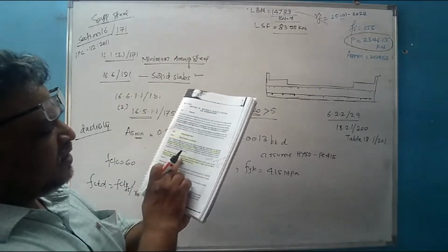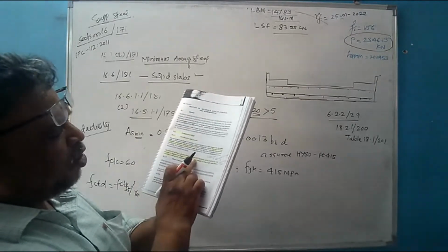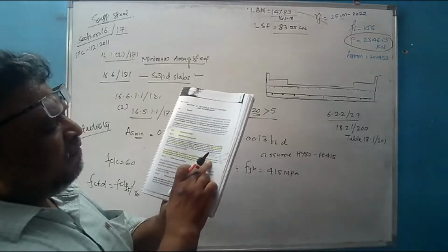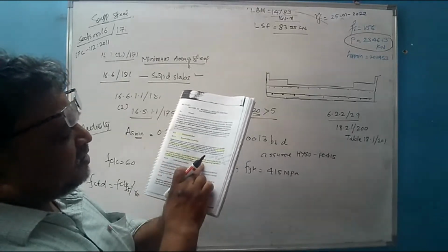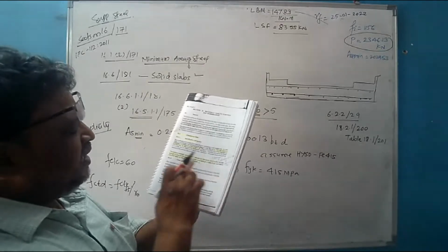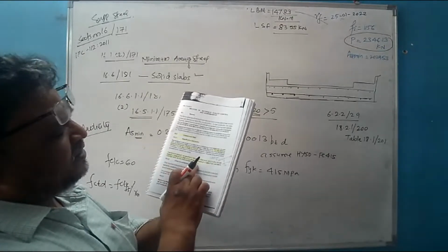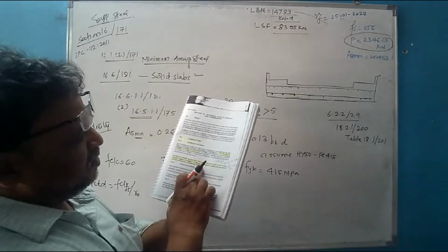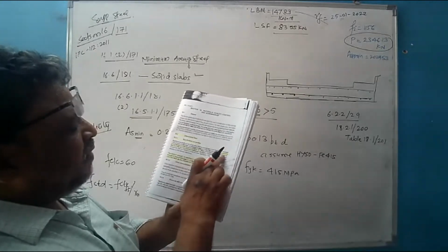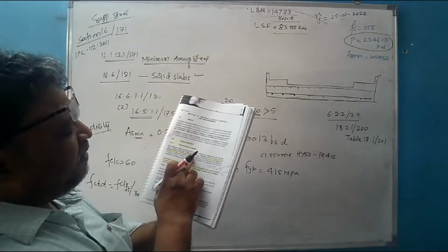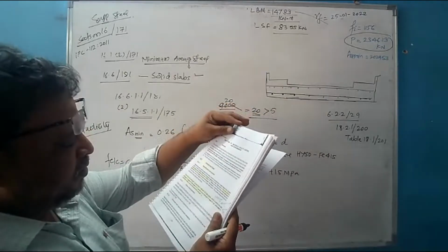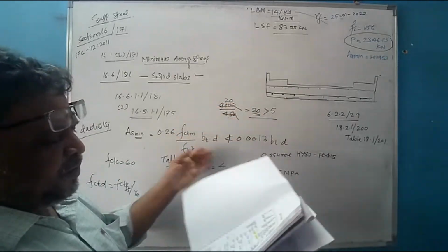The minimum strength as specified in the relevant BIS, Bureau of Indian Standards, which is either the yield strength in case of mild steel or 0.2% proof strength in case of high yield steel, is nationally taken as the characteristic strength. फिर क्या बोलता है? The main definitive properties and grades are given in Table 18.1. 18.1 next page पर दिया है.